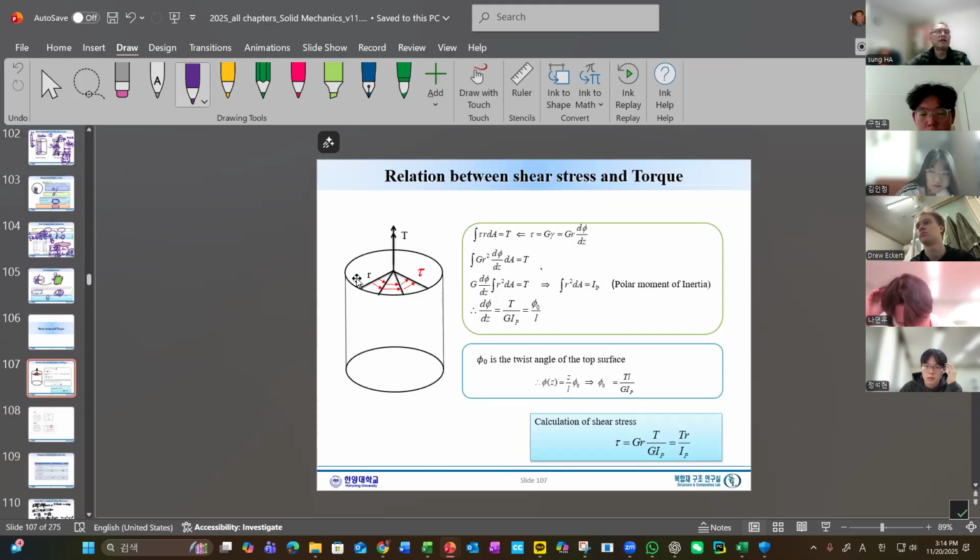Okay, let's move on. Now, what is the next one? See, we always have an equilibrium. Equilibrium means the torsion T. See, we got this, gamma is d phi dz times R, and then this guy shear strain. What does it mean? Shear strain is caused by the G gamma is the tau. So this tau will distribute over the section like this. So d phi dz is a constant, and strain is proportional to R. That's important.